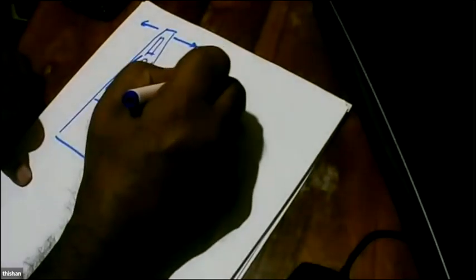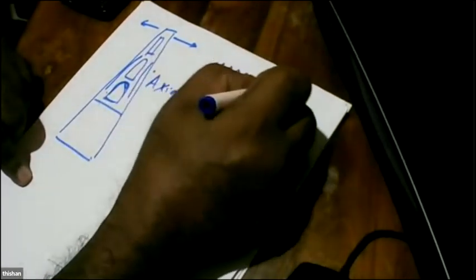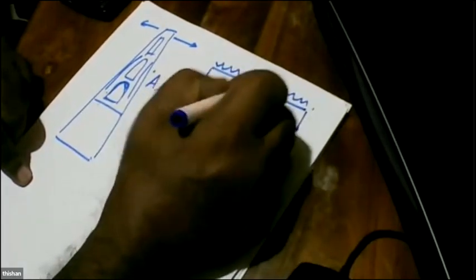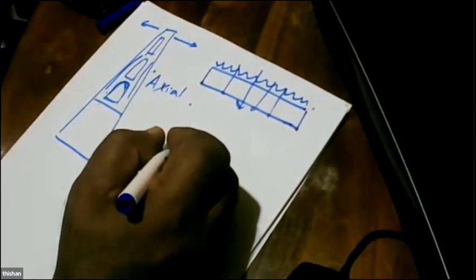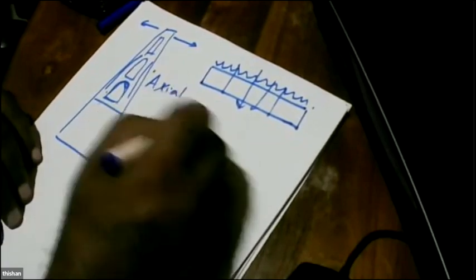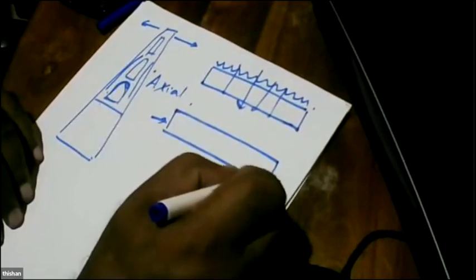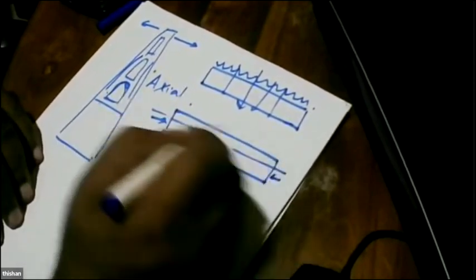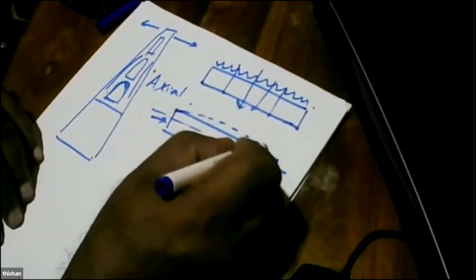On the other hand, we have a beam. And we know it's going to be loaded only in one direction, and that is downwards. So if that is going to be behaving downwards, what we can do is, if you know the behavior, we apply the pre-stress at an eccentricity and make it bend upwards.